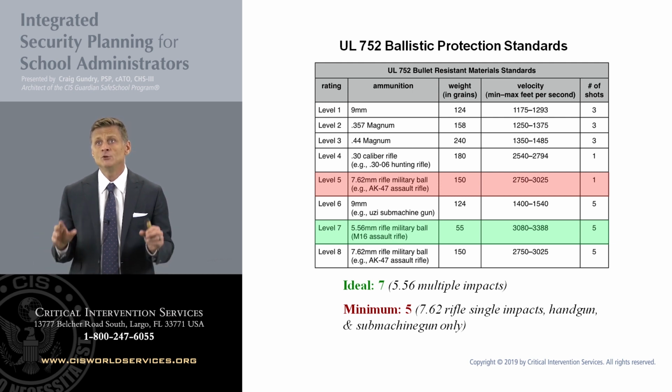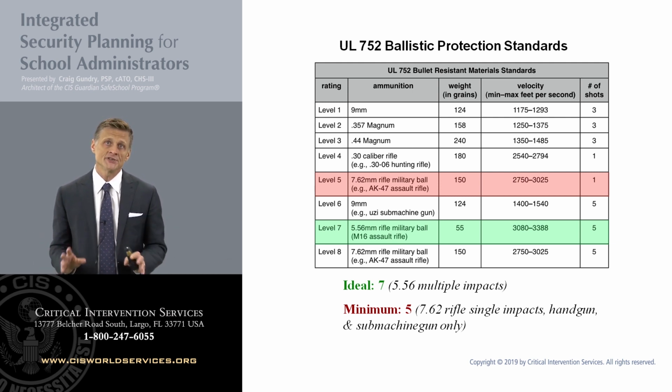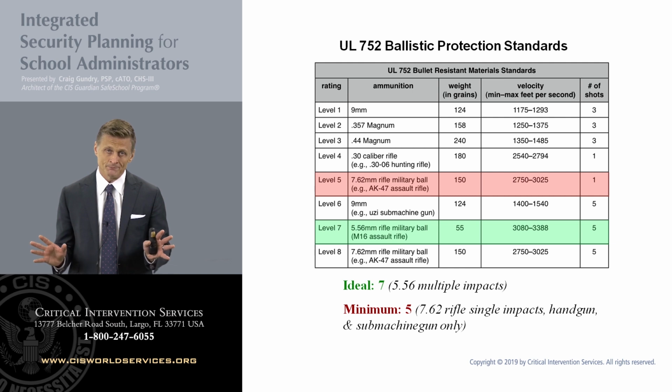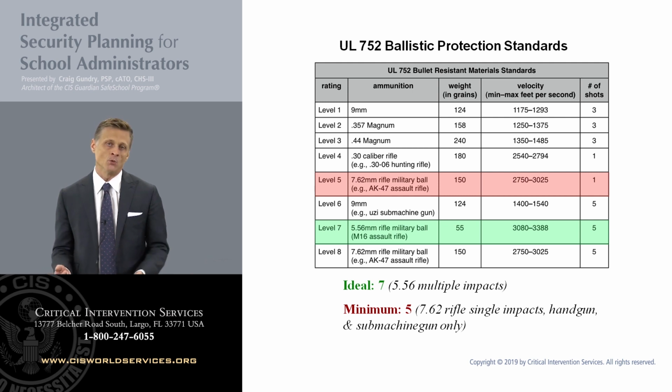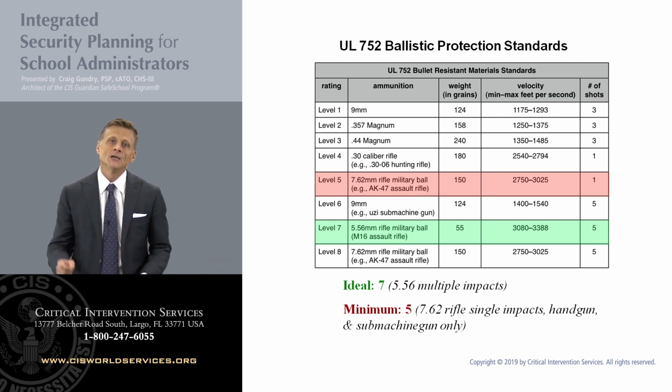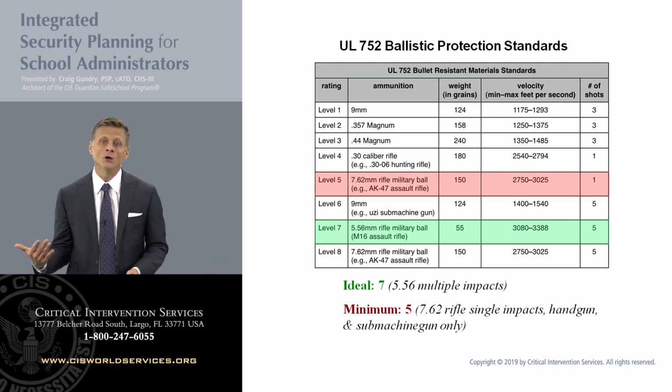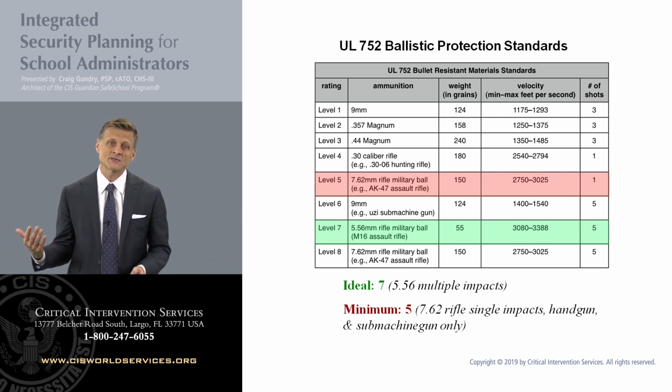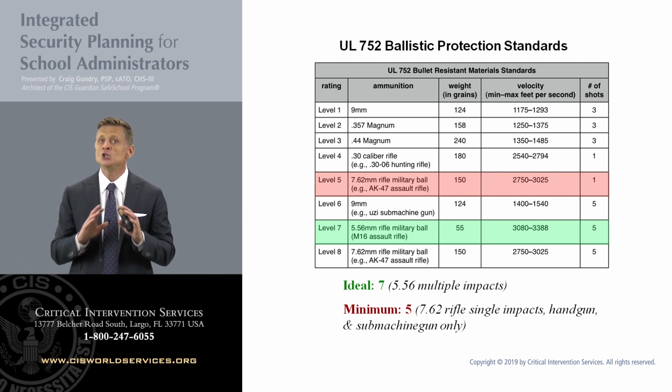Now, keep in mind, if you plan on installing ballistic resistant barriers anywhere, the weight and framing requirements, the structural construction requirements, are very different from common structural materials. To just give you an idea of comparison, a level 7 fiberglass panel often weighs as much as 11 pounds per square foot, by comparison to standard drywall, which weighs approximately 1.6 pounds per square foot. Huge difference.